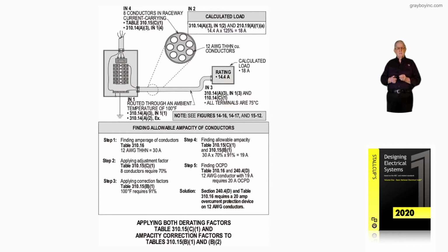Now remember, Article 100 defines a continuous load as any load that could operate for 3 hours or more. So in selecting, based upon 47 amps, we go to Table 310.16. We review 240.4(B), which says you can raise the overcurrent device above the ampacity of the conductors. The new ampacity of the calculation is 47, so we're raising due to that calculation.